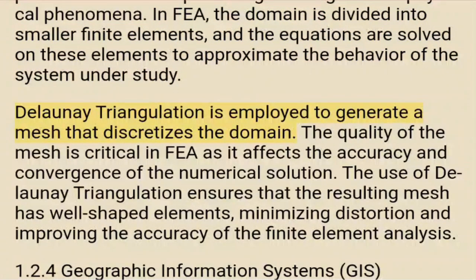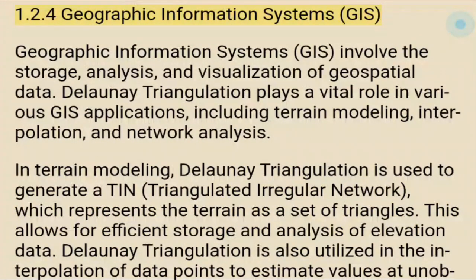Delaunay triangulation is employed to generate a mesh that discretizes the domain. The quality of the mesh is critical in FEA as it affects the accuracy and convergence of the numerical solution. The use of Delaunay triangulation ensures that the resulting mesh has well-shaped elements, minimizing distortion and improving the accuracy of the finite element analysis.